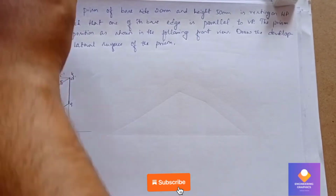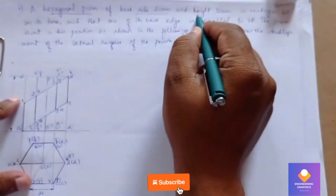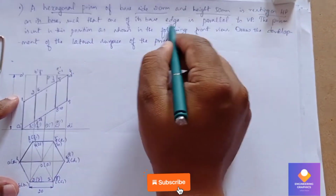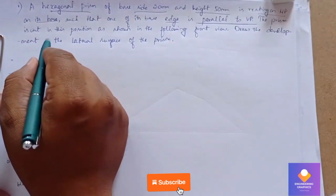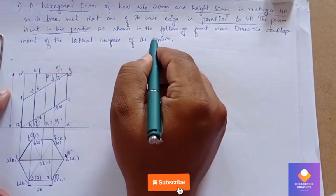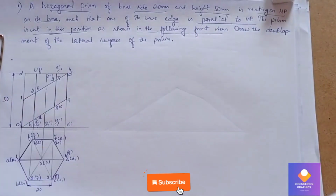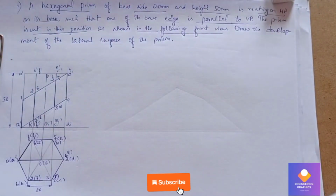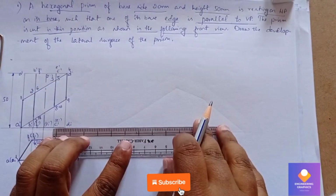Hexagonal prism of base side 20 mm and height 50 mm, resting on HP on its base such that one of its edges is parallel to VP. The prism is cut in this position as shown in the following front view. So we have drawn it and it is given in the question. So it has been cut like this. Now we need to draw the development of the lateral surface of the prism. So I will extend these lines.